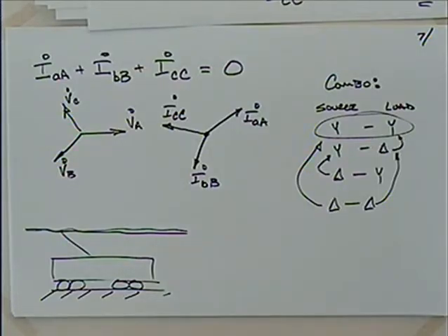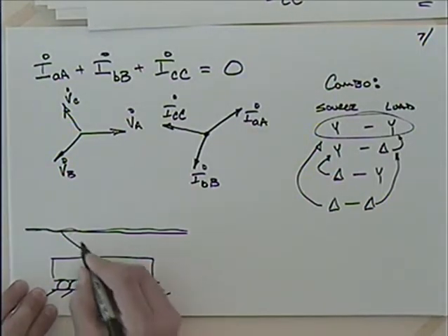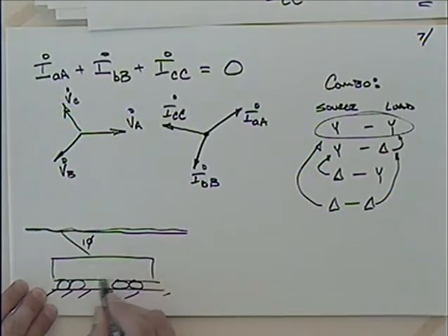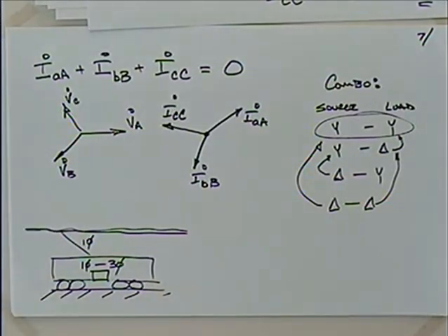So we'd like to have a system where we only have single phase. So what we do is we'll have single phase here, and then once we get on board the streetcar, it was very common for them to have a single phase to a 3-phase converter. Why would we want to have 3-phase motors down in the wheels on the streetcar? So you can go back and forth, right?